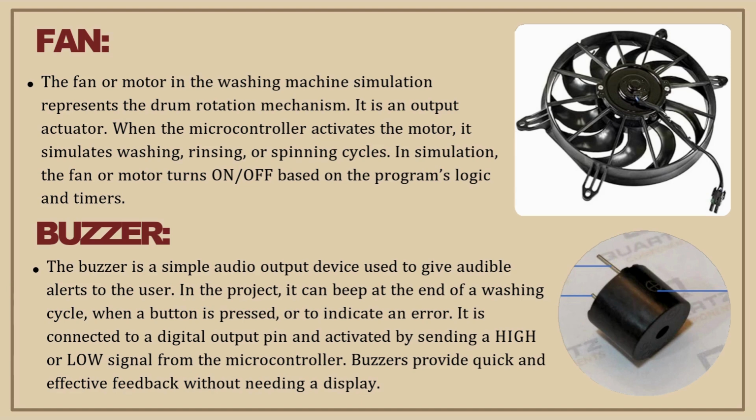Buzzer. The buzzer is a simple audio output device used to give audible alerts to the user. In the project, it can beep at the end of a washing machine cycle, when a button is pressed, or to indicate an error. It is connected to a digital output pin and activated by sending a high or low signal from the microcontroller. Buzzers provide quick and effective feedback without needing a display.